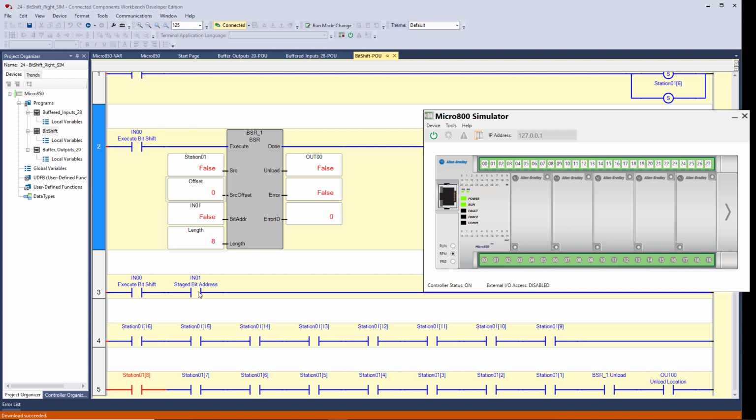So we have a 0 staged now, okay? Now, if we are going to put this value, which is 0, into this bit, if we don't move this one first to 7 and so forth, in order not to wipe out what's in 7, we would have had to have moved it to 6 before we move 8 to 7. You get the idea. So I'm going to toggle the execute back on. You see it's done, back off, and you see it moved all 8 of these bits, and this 0 right here that was there went to the unload.